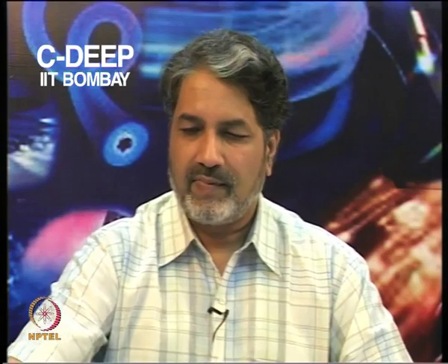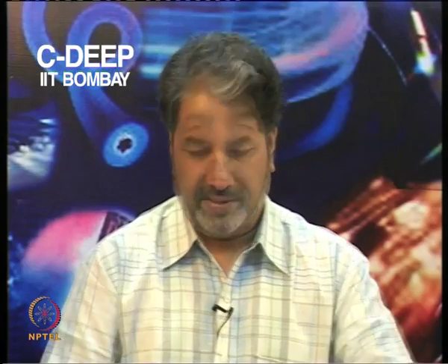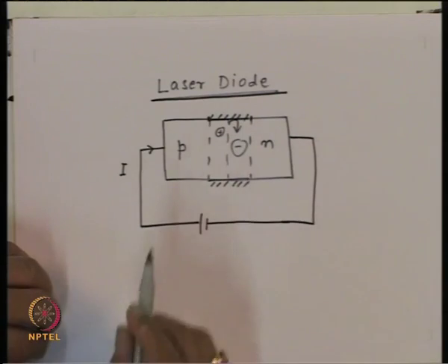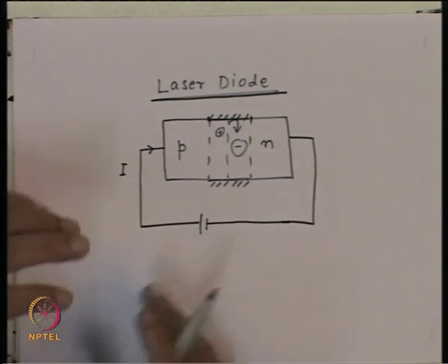So, you will see essentially what we are talking about here is that once the electron hole pairs are injected inside the region, then as long as the electron hole pairs remain inside this region once they are injected, we will not be able to change the light output even if we switch off the current externally. And the lifetime which we have here is essentially decided by the stimulated lifetime of the carriers.